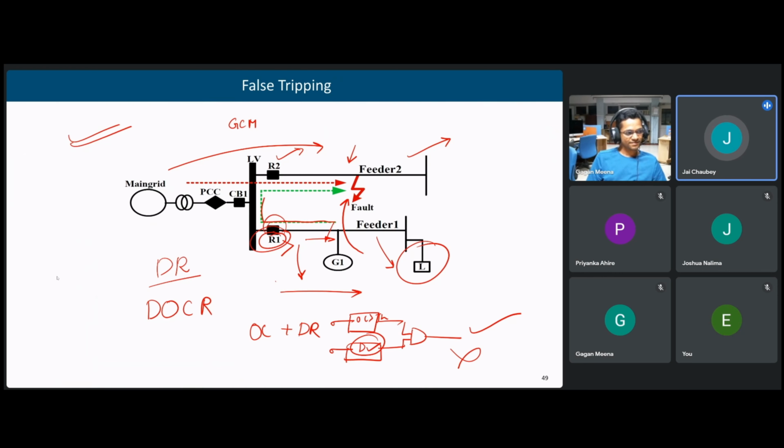It means fault stripping takes place only when one of the feeders is going under fault. Yes. It may affect the other feeder also in case it does not have the directional element. So this will only happen if this current exceeds this threshold of R1. It may not always happen. It may happen with overcurrent only, in not faulty conditions also.